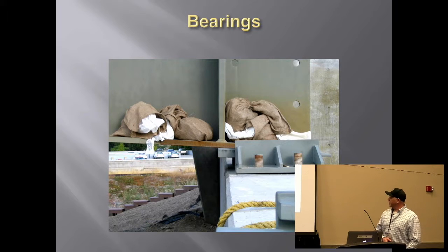Next thing we'll talk about is bearings. I know Mark touched the base a little bit on this, and we'll go over it a little bit more. One of the big things with bearings is getting them placed properly, also cleaned off. The bearing area, the surface areas, they're cleaned off, all the rocks, everything. It's kind of funny, we go out and check them, and a lot of times there's gravel and everything underneath the pads.